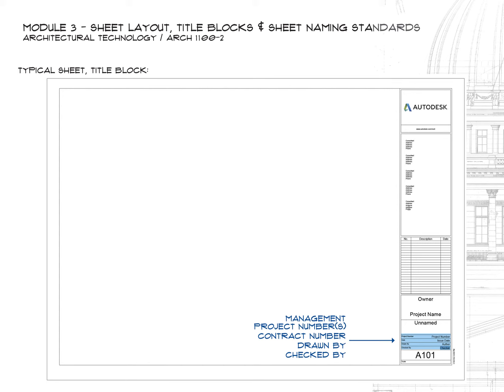And most of the time that is built into the title block, but some people just put it off to the side. So the reason why I'm mentioning the wet stamp right now is usually whoever checks it is also the person stamping it. So again, one thing that we don't see actually accounted for here is a place for the stamp. Now if I were to redo this Revit title block, I might put it up here. I might get rid of one of these consultants and put an area for a wet stamp. You could also just put it somewhere out in the drawings and not have a designated spot for it.